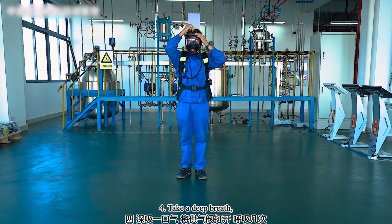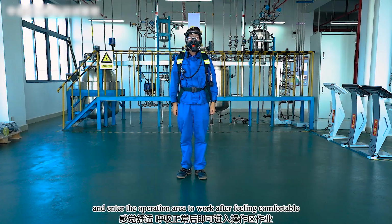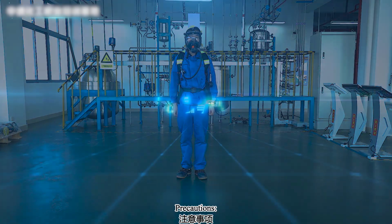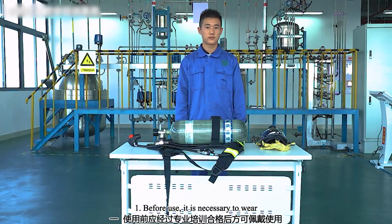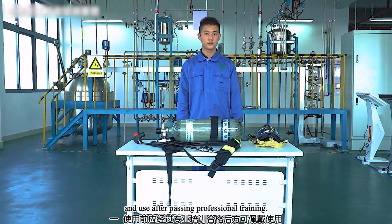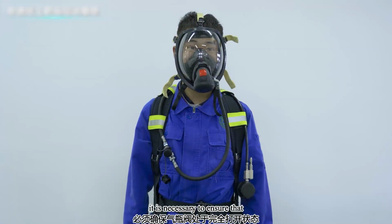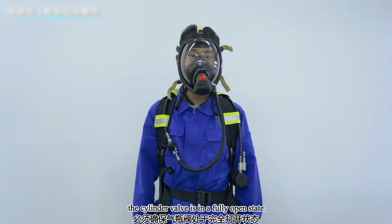Fourth, take a deep breath, open the air supply valve, breathe several times, and enter the operation area to work after feeling comfortable and having normal breathing. Precautions. First, before use, it is necessary to wear and use after passing professional training. Second, during use, it is necessary to ensure that the cylinder valve is in a fully open state.